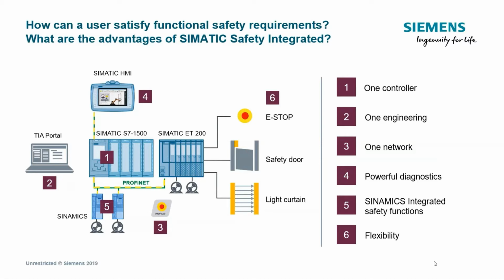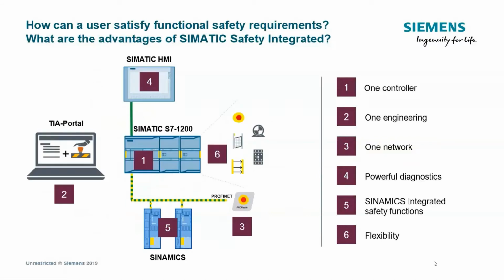That concept we have had for a long time now, and currently we have the options based on all the control systems available in TIA Portal, be it S7-1200, 1500, ET 200SP, IO systems. All of them are integrated and available within TIA Portal. This is one example for an S7-1500 based application, but if you're talking about smaller systems with fewer requirements, so maybe fewer safety functions, then you can also use an S7-1200 fail-safe. Fail-safe CPUs and IO modules are available also for S7-1200.